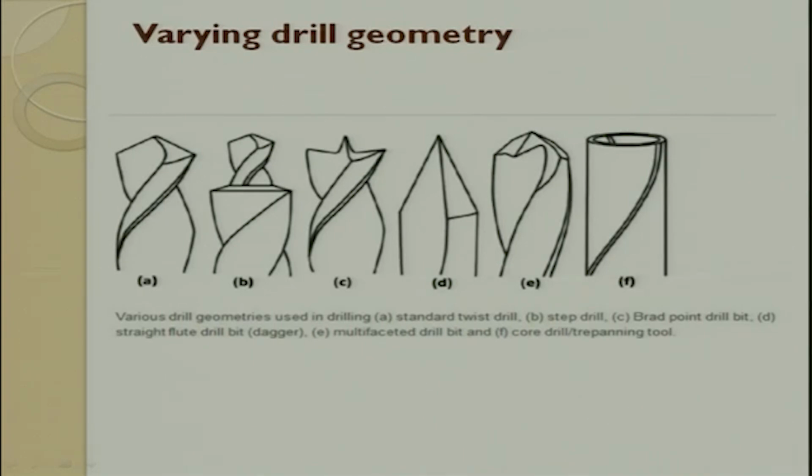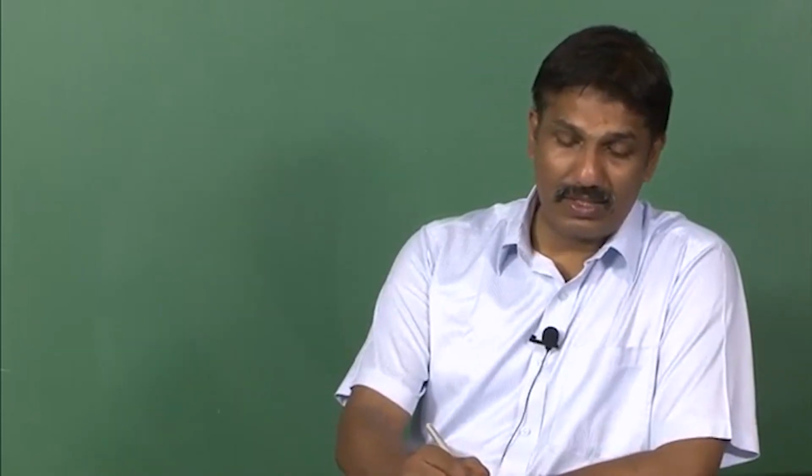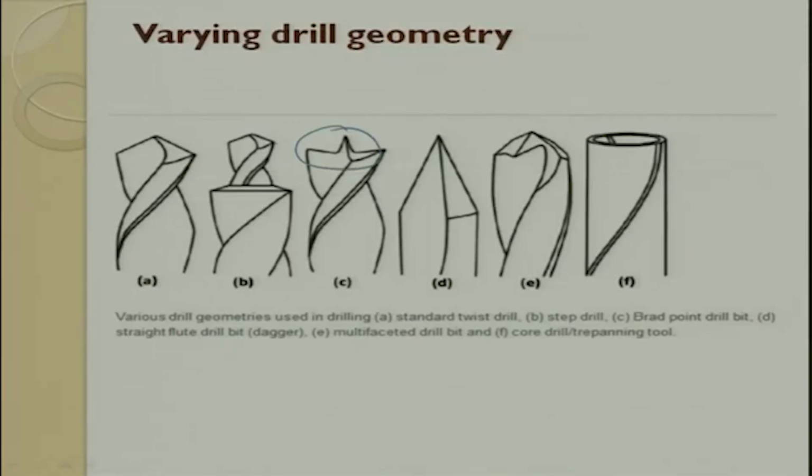Now you see there are various drill geometries which have come into existence. These drill geometries make sure that the thrust force is reduced to a large extent. If you reduce the thrust force, the push down delamination can be reduced in a large way. This is something like a tripod. So, we have 1, 2 and the center portion. The chisel edge is now converted into a point, and these two edges are converted into two other points. So, here the thrust force reduces in a large way.